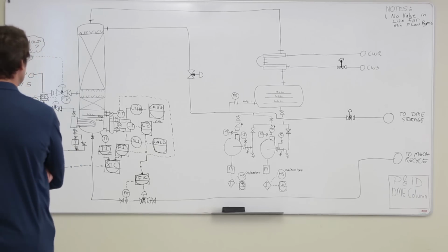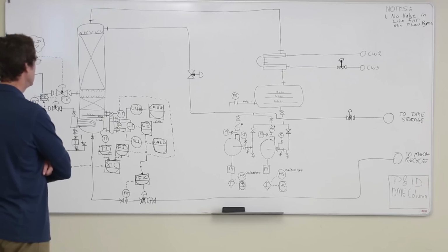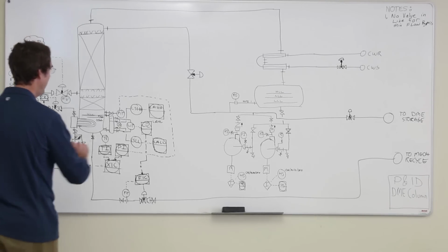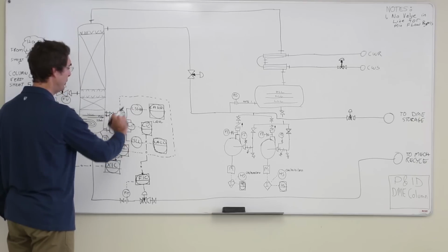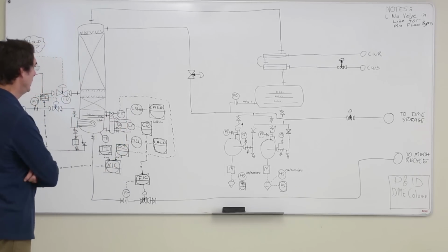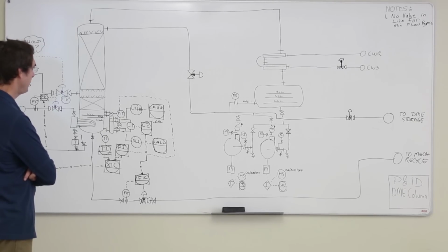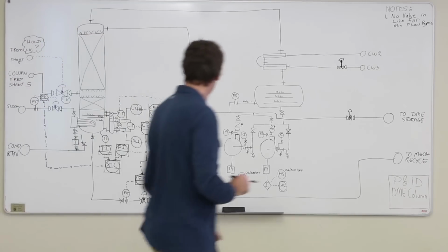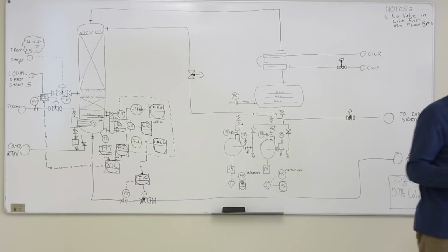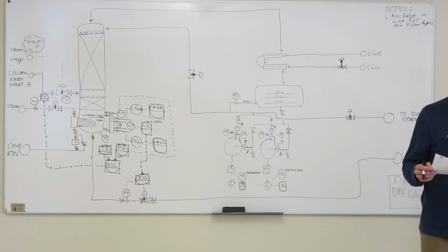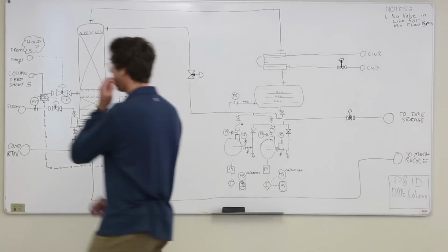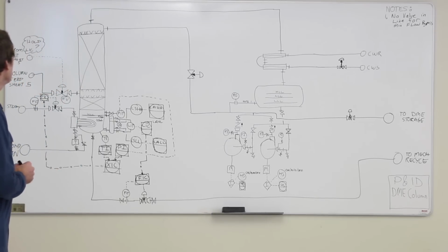And I have provided valves on the level switches, which means that they could be bypassed. So we might be car sealing those open. That's not too bad. See if I missed anything from my little sketch. Pretty close. Any questions about the bottom of the tower?